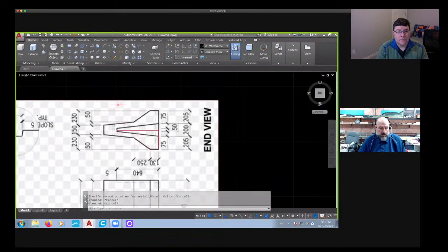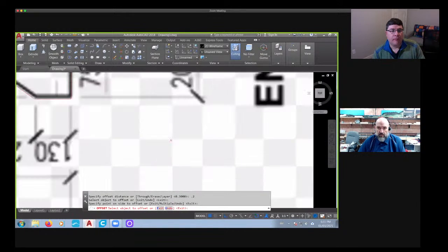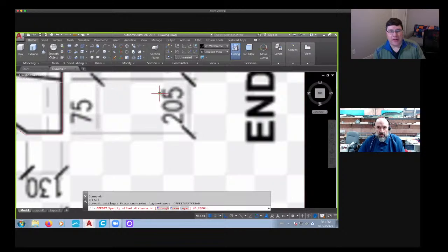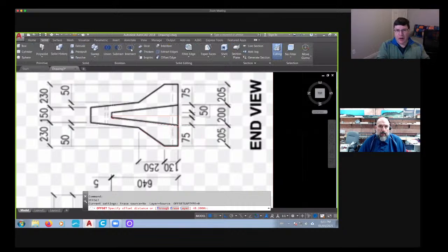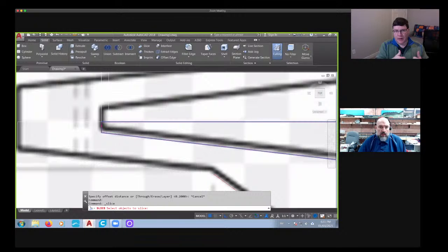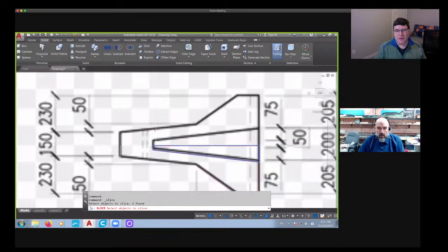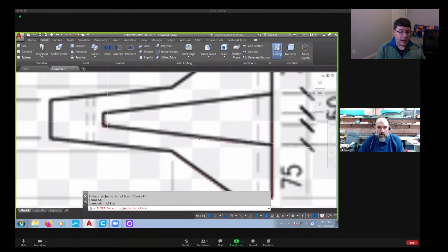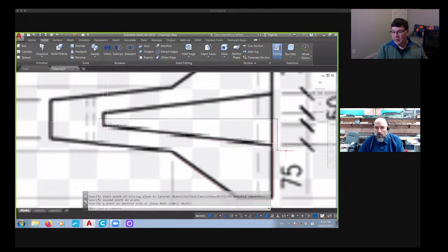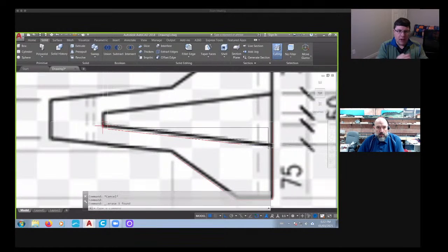And let's go offset 0.2. Let's do 0.2 mil. And then offset. This just makes it so that when we are lining them up, it will give a fairly tight fit. Like on the models that you've done before, I'm just going to make sure that I'm not missing anything in chat. On some of the models that you've done before, of course, you've got pieces that interlock and little aligning knobs and things like that.